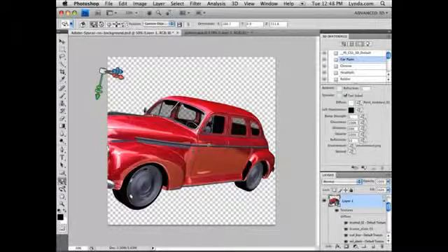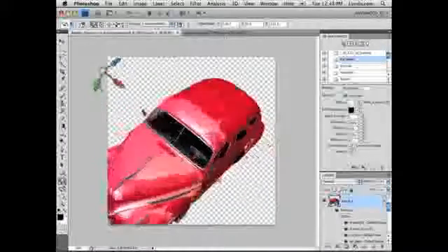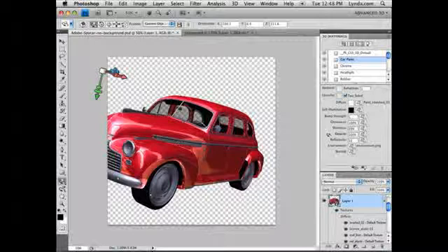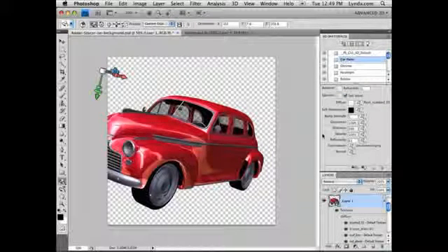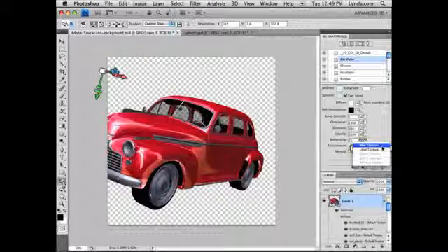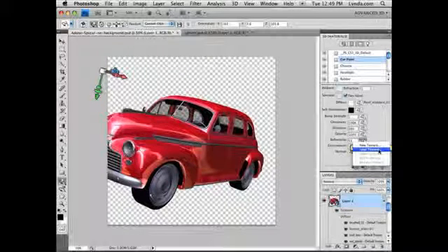Now this is a little bit too reflective, but you can see how you can increase that just by coming to the material editor and adjusting that here. If the object does not have a particular map applied, say for example for reflectivity, and you want to use a map to control this property, you can click this little flyout menu and create a brand new texture from scratch, or click Load Texture to import one.